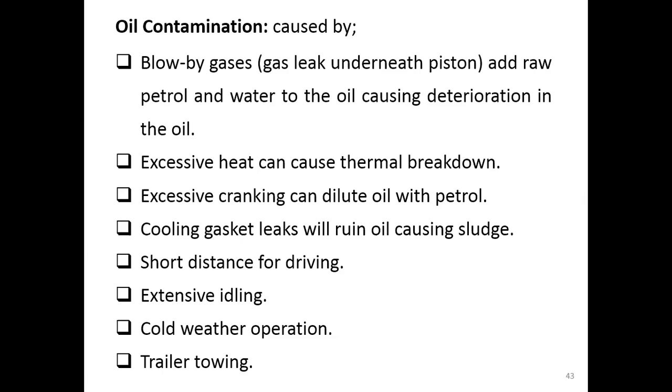Okay, as well as if you have extensive idling of the engine, or running the engine with no load, it can also contaminate the lubrication oil. Cold weather engine operation can also deteriorate the oil, because the oil viscosity increases, or goes up, as the temperature goes down.